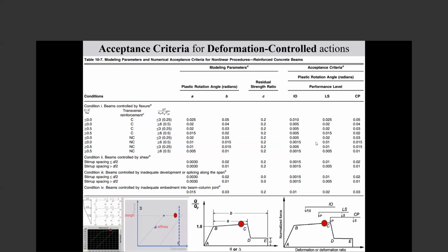Of course, you can introduce the material properties, because as input you should give the stress-strain curve for the material, and then give the distribution of concrete and reinforcement in the section.